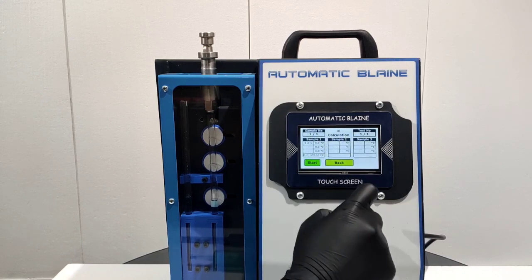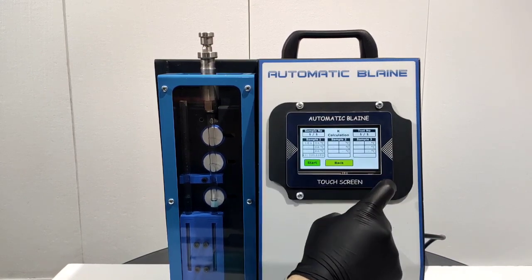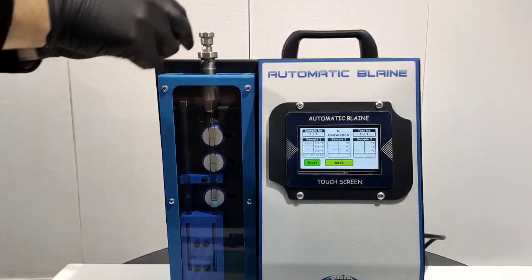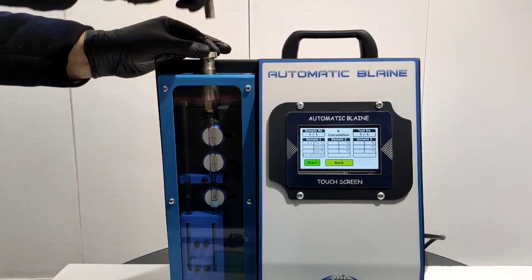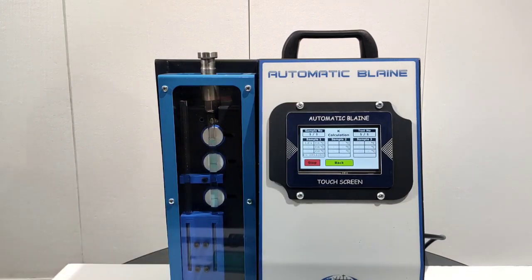Press the start button. Measure the ambient temperature and use this measured temperature value in your calculation. The pump draws the liquid above the highest level and stops at the highest level. Then, as time passes, the liquid level in the U tube drops. The time starts when the liquid goes down to the second level. After passing the lowest level, the measured time is displayed.